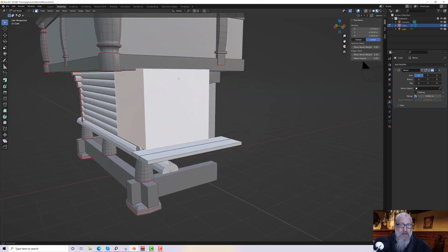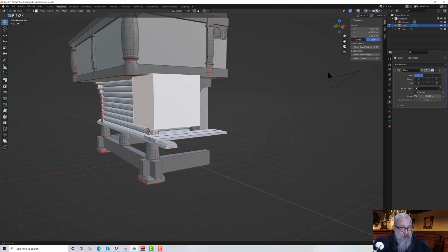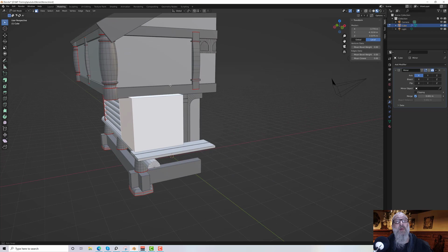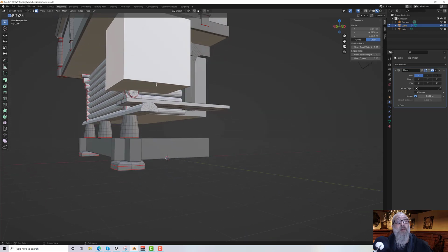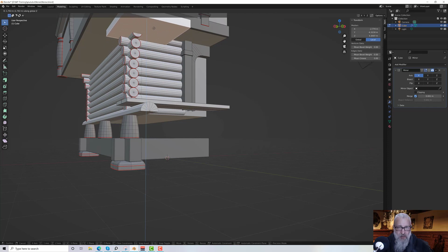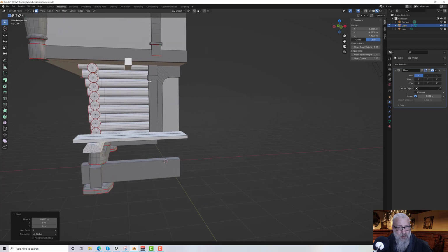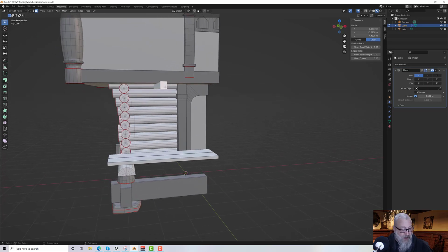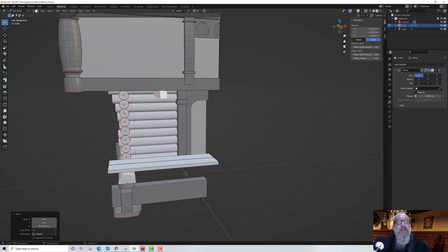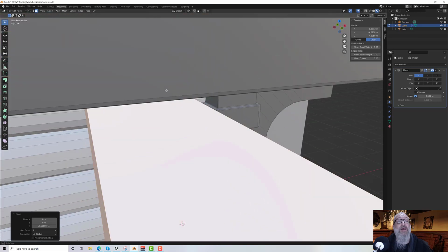Now we can just shape it a little bit. So I'll do this because I've got it roughly where I want it. I don't want to adjust it too much. So we'll move the bottom polygon up, G and Z, just to a suitable kind of depth, and then we'll do G and X on this side one, just to make it a good shape and size. Let's bring it down a bit. So I'll select one polygon and then press Control L. And then G and Z, I'm just going to bring it down ever so slightly, just so it's underneath that